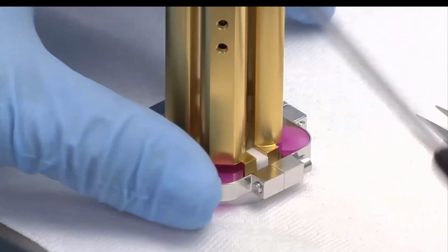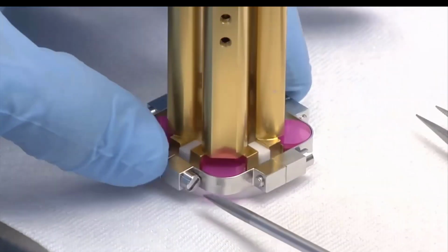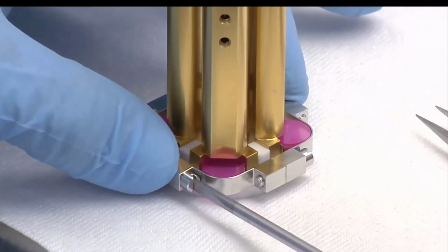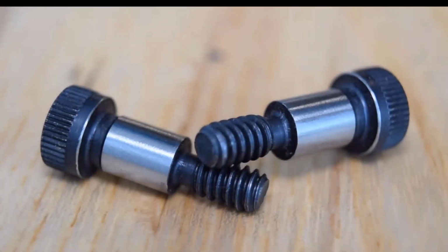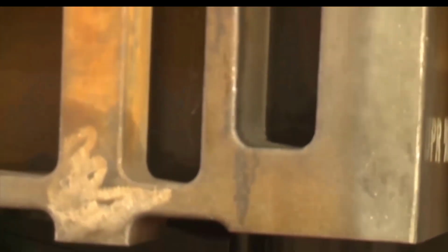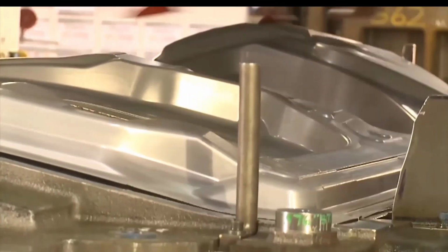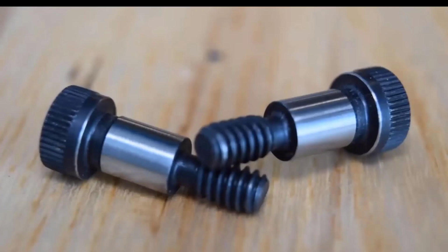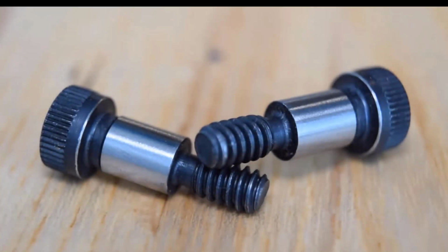In cases where you need a fastener to also precisely align components, you might consider a shoulder screw. They have a precision ground shank under the head that can be used as a pin, shaft, or linear guide, and they're a common component in punch and die assemblies. Shoulder screws usually have a much smaller threaded section than other screws, so you can't use them to generate a lot of clamping force. Also note that they're not nearly as strong in shear as a dowel pin, so you shouldn't subject them to heavy loads.